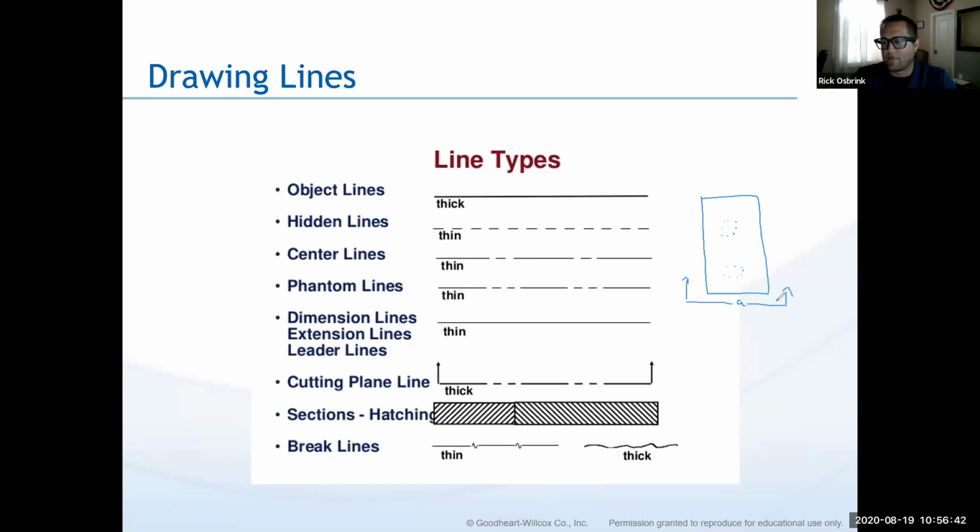Basically what this references is that if I were to take this piece and cut it in half along this line, like this is my knife, and I cut it along this line, and then I were to open that up, that's where I would go over and I would see my section view, and that's the view that I would see. So you're able to get a reference, an orientation of where that section view is coming from. Okay, it's cutting it this way, and I'm looking at it that way. We talked about the hatching. So obviously this shows a solid area.